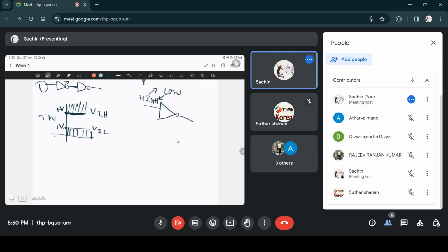What do you do? You can come to the very top and start giving it 1 volt. So you reduced your voltage from 4 volts to 1 volt, which is a reduction of 3 volts to change the state from high to low. Or suppose you started off at 1 volt, which is a low voltage, and then you wanted to change your input to high. So what you can do is keep changing this 1 volt until you reach 4 volts, at which point the circuit will consider it as high voltage.